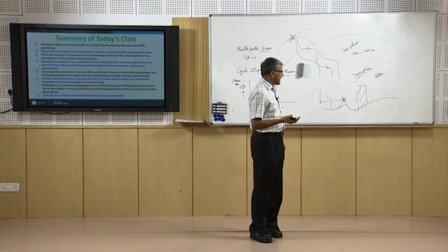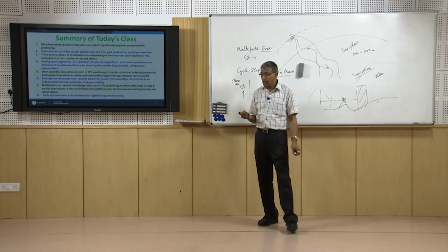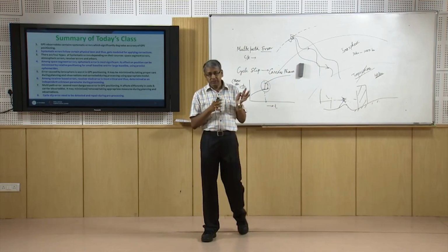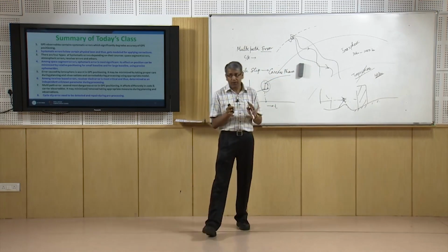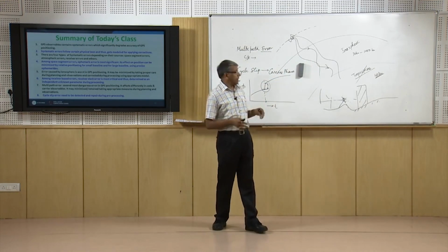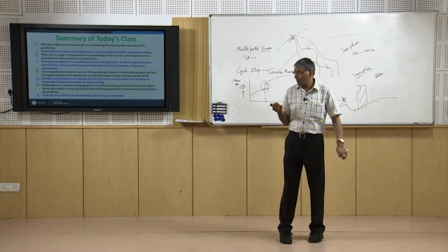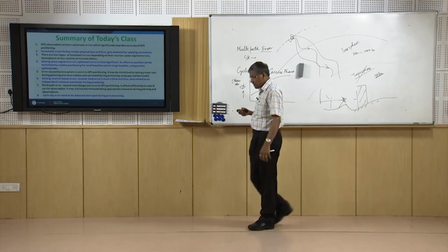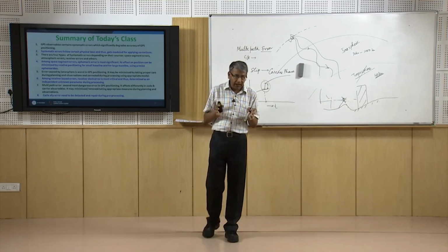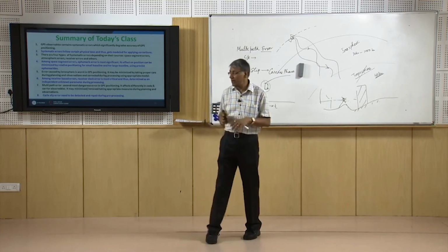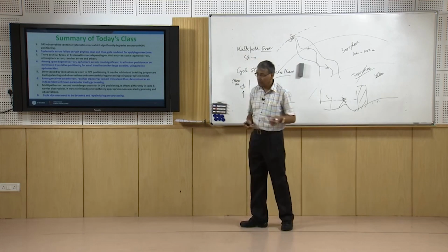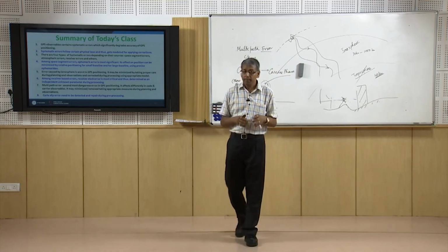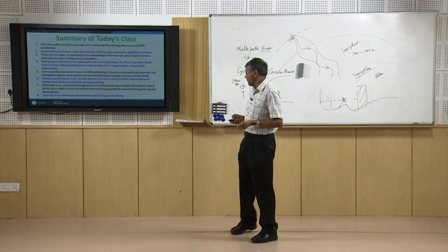The next worst is the ionospheric error, which varies from signal to signal and between different components of the signal, and it can be minimized through proper planning and modeling. The next variety is the multipath error, which has to be removed or minimized.